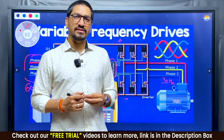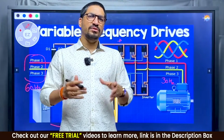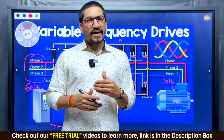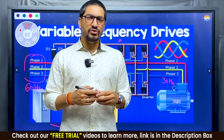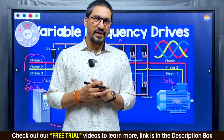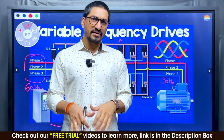And where do you use this thing on board ship? There are chemical tankers in which there is a motor fitted on the deck and the pump is inside the tank. These induction motors we need to run at different speeds so that I can change my delivery volume per hour. It means I need to change my delivery rate for these motors. I can speed them up, I can reduce the speed. This is required. So that's why one of the companies, called Marflex, is making such pumps where, using a VFD, I'm driving those deck mounted pumps in a chemical tanker where cargo pumps are inside the tank and the motor is